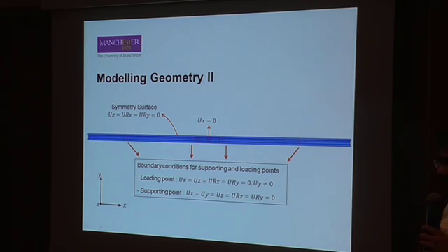In terms of boundary conditions, to limit movement of the pipe in the axial direction, I just fix the center of the pipe in the x direction. Supporting points should be limited for any rotation and displacement. The load should be implemented based on displacement in the y direction, and the rest of the rotations and displacements should be set to 0.